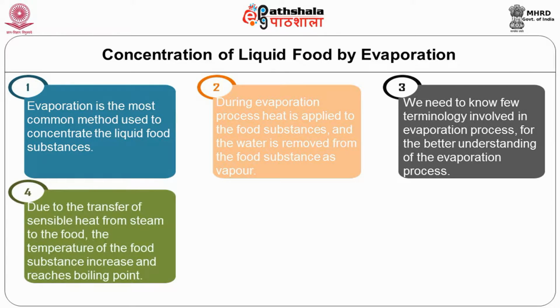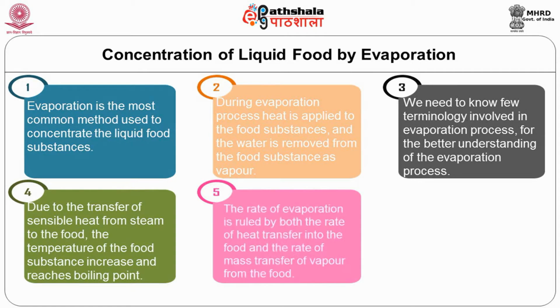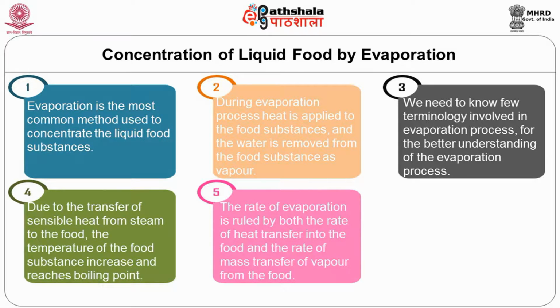Due to the transfer of sensible heat from the steam to the food, the temperature of the food substance increases and reaches boiling point. Then, the latent heat of vaporization is supplied by the steam to convert the bubbles of water to vapor. So, the rate of evaporation is ruled by both the rate of heat transfer into the food and the rate of mass transfer of vapor from the food.